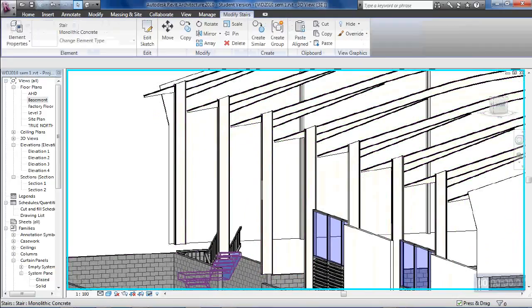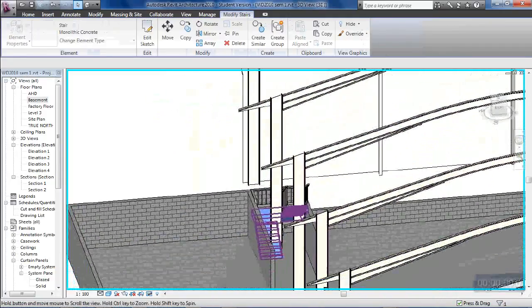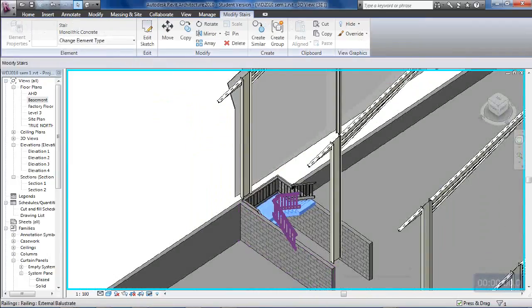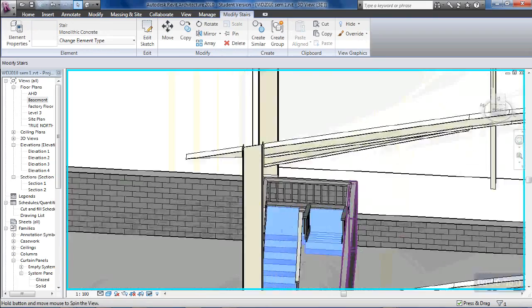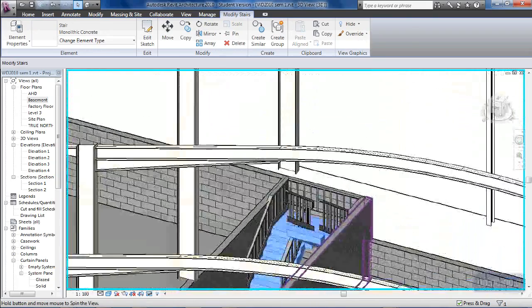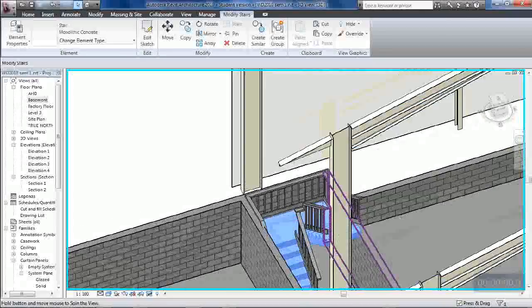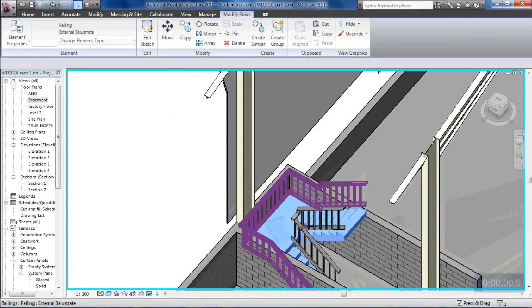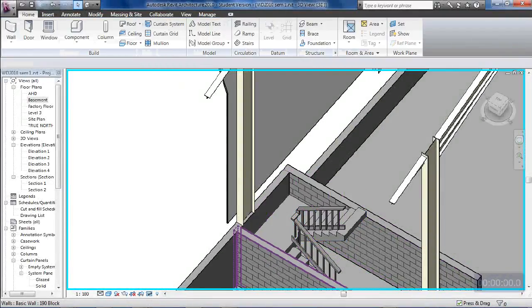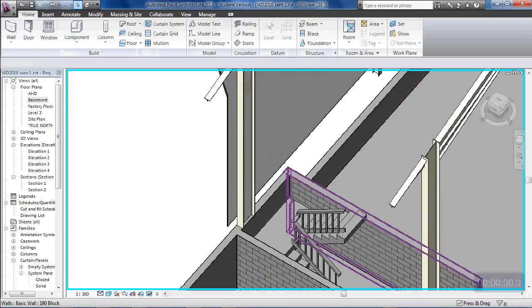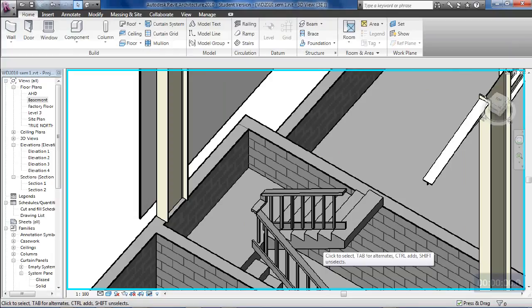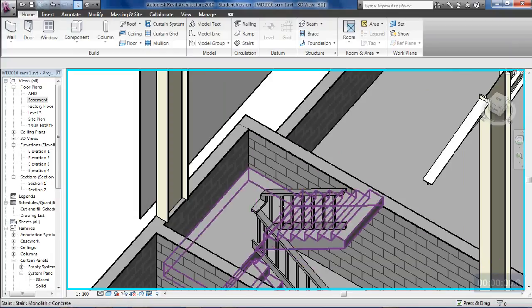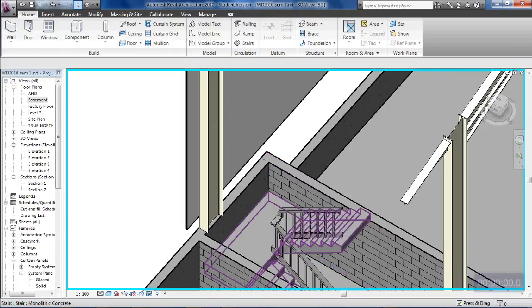The handrails at the moment will be not appropriate for this building. We'll address that a little bit later. But yeah, that's looking like the correct sort of monolithic stairs that we wanted to create. In fact, I'm going to delete the external set of railings and just leave the internal railing. For a 1 metre wide fire stair, you just need a railing on one side anyway. And so I would put it on the internal face, because that way the railing will satisfy the balustrading requirements for that set of stairs as well. So that's probably the stairs done at this stage.